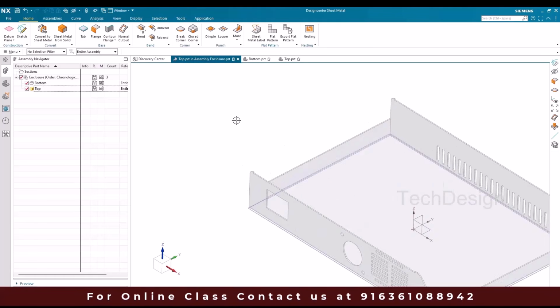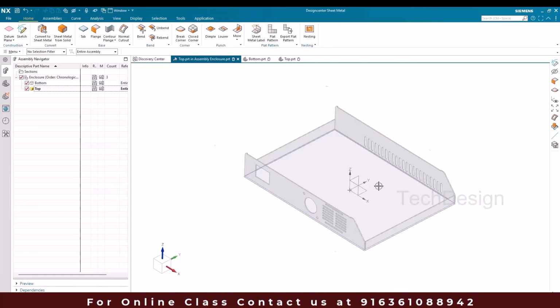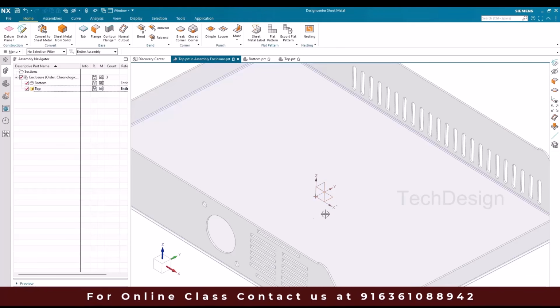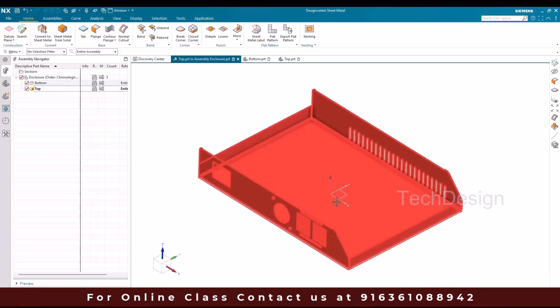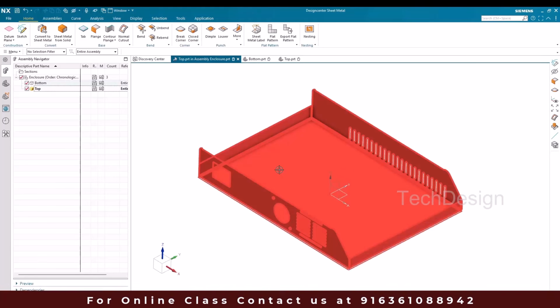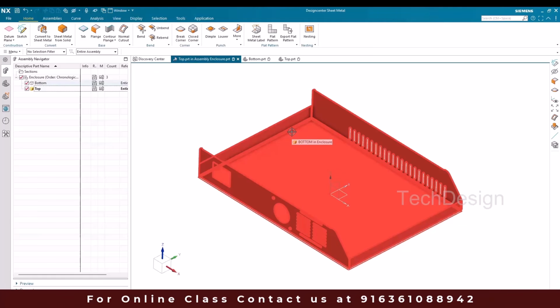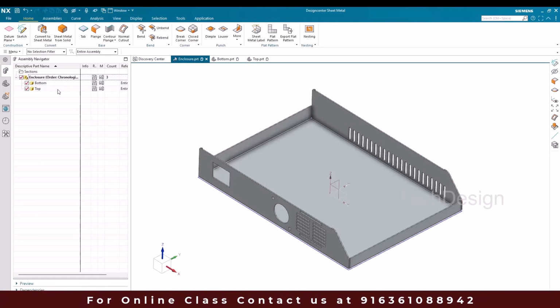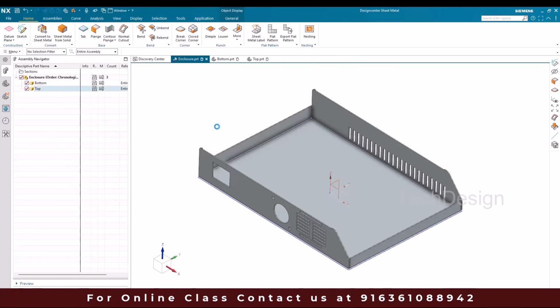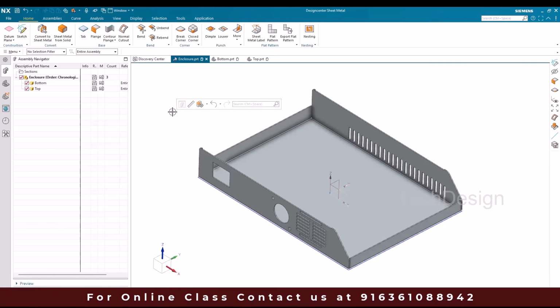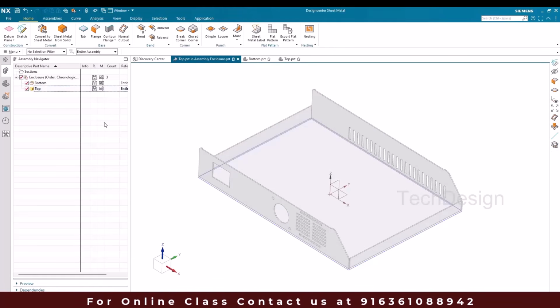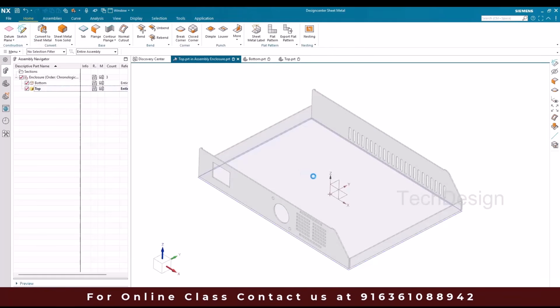You can see here our top part, if the coordinate system is at this point and you create the part, it is going to come here. Later you can just move it to the top side and start creating. So now I'll make this a little bit on the top side, or we'll do it like this. We'll just go to the sketcher environment on this plane.